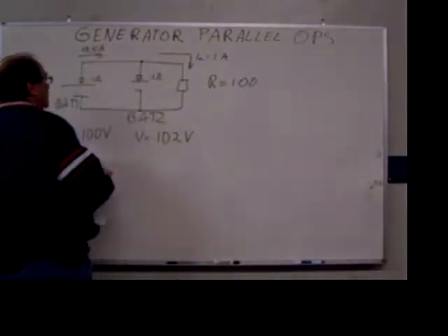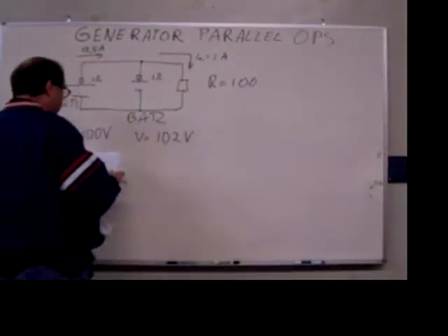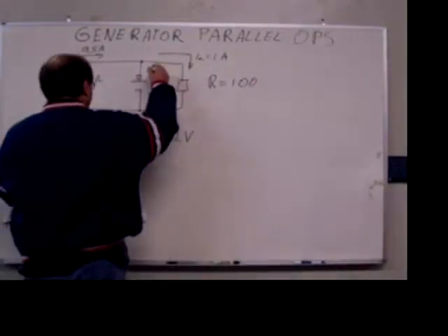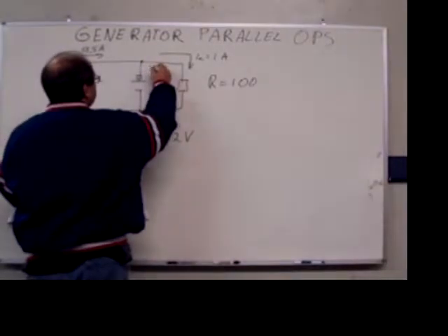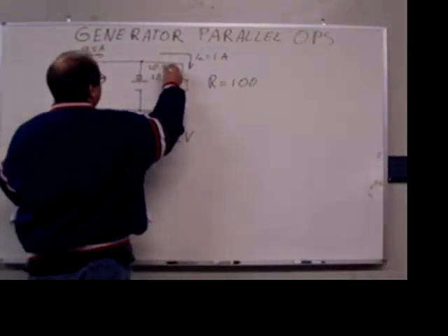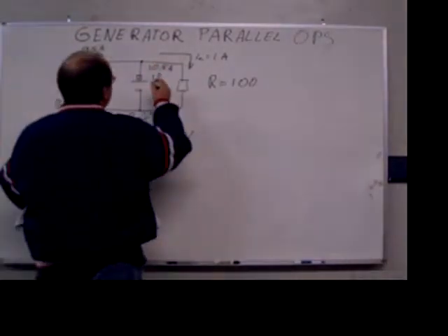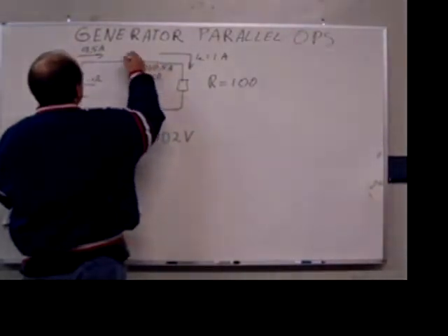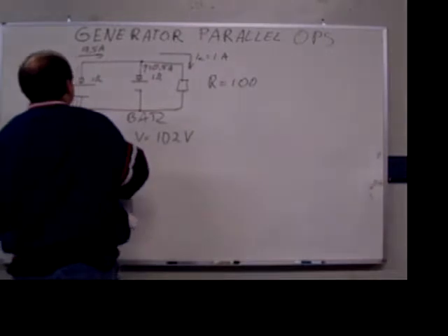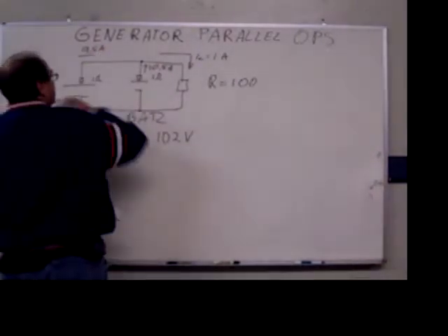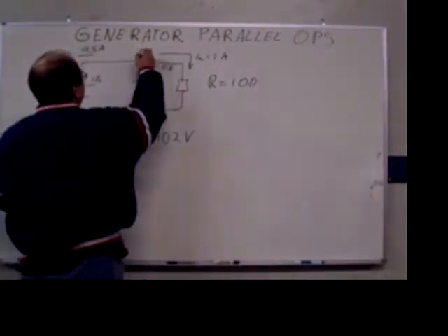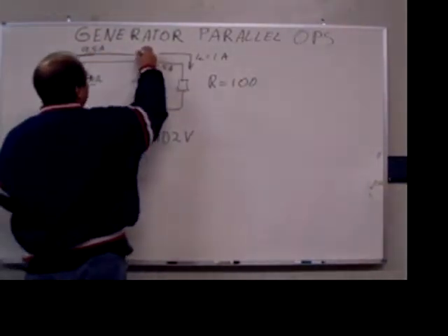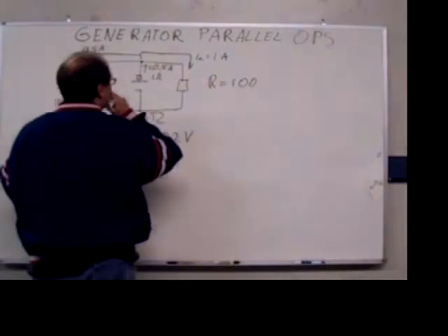You're going to ask why. Because the entire current is going to be 10.5 amps here, and this breaks out as follows. It goes up from this battery, then it splits. The 9.5 amps go from this battery over to this one, and 1 amp goes over to your load.